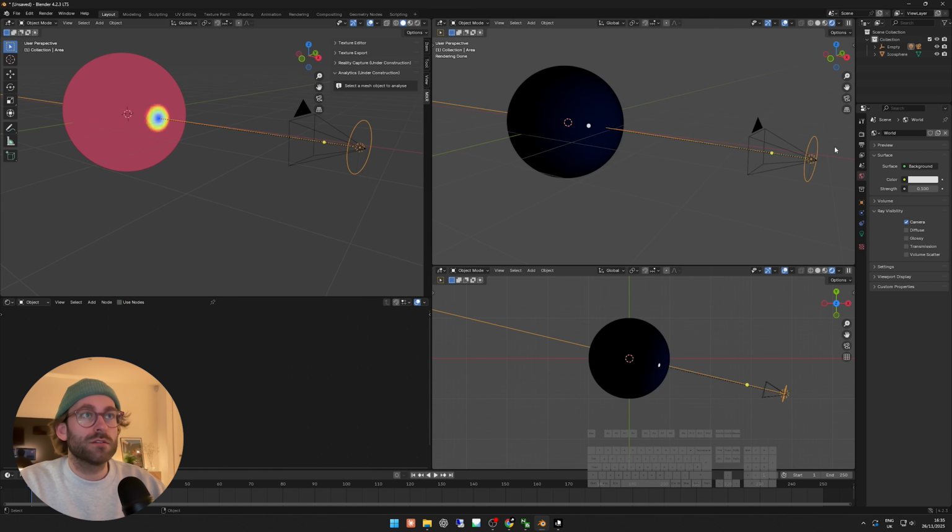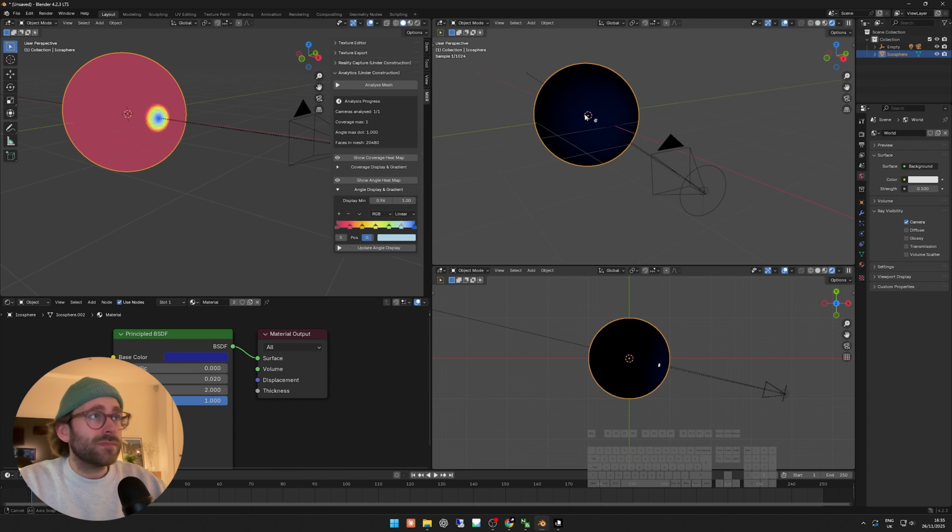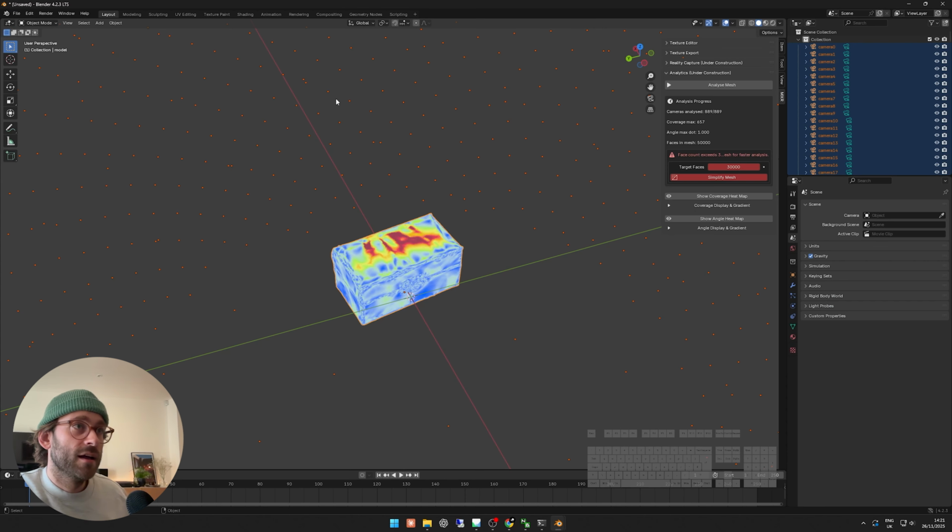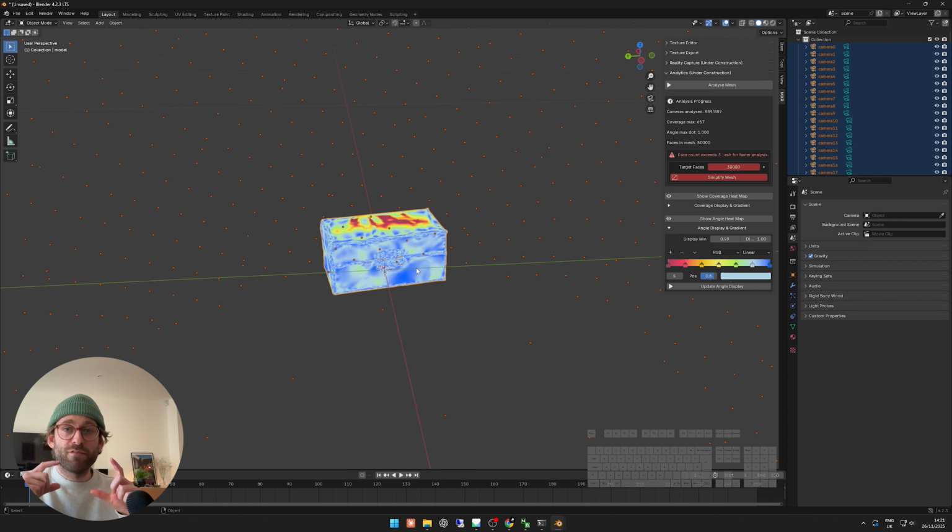Now if we change the size of the light source, that's the only way we can actually make that reflection smaller. But it's so glossy that we would have to almost position loads of these lights in 3D space in order to cover this whole thing. So in this scenario, we would say anything within that really deep blue is the only thing that we can predict here. We could even increase our threshold on the display to make it really tiny. If I go on the drop down here, anything here is saying that we have cameras where we can see that reflected ray of light.